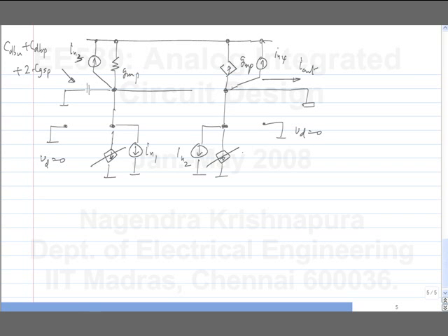This is the method for noise analysis in general. You model the noise of every transistor in the circuit and look at the output current because of each noise current, and you add them all up. Of course, the noise current itself is not of interest, its spectral density is. Now, you are considering noise from different devices which are all uncorrelated, so you add up the spectral densities.